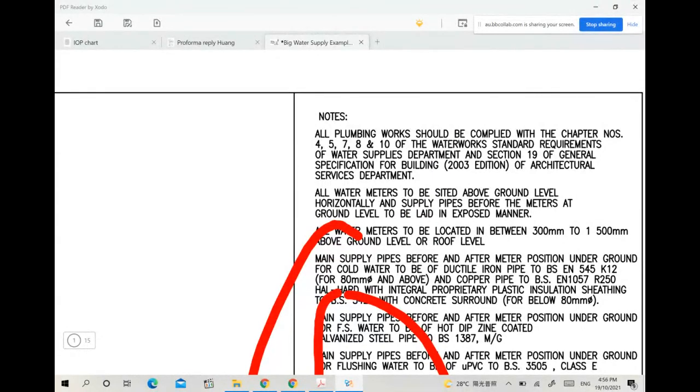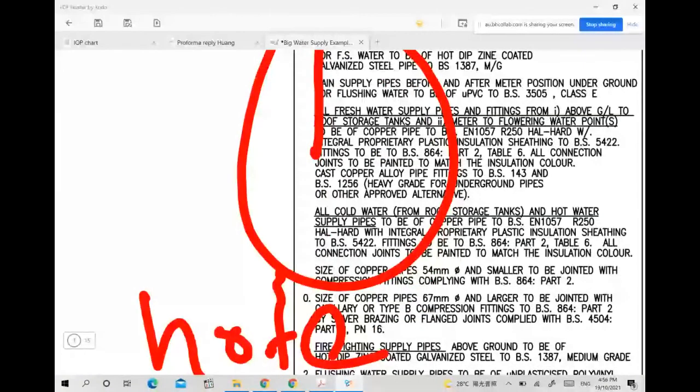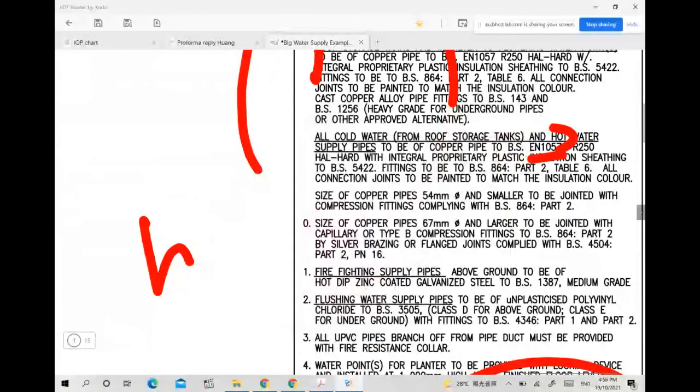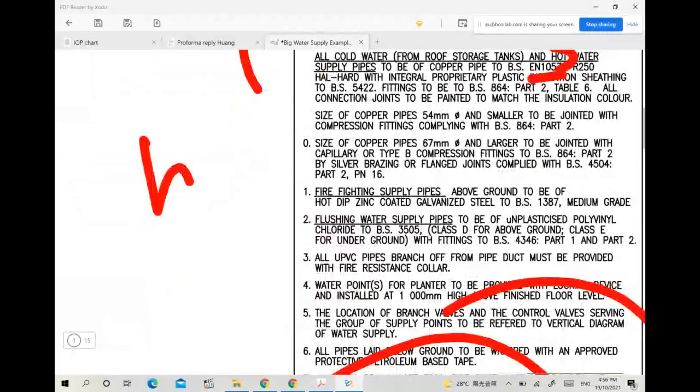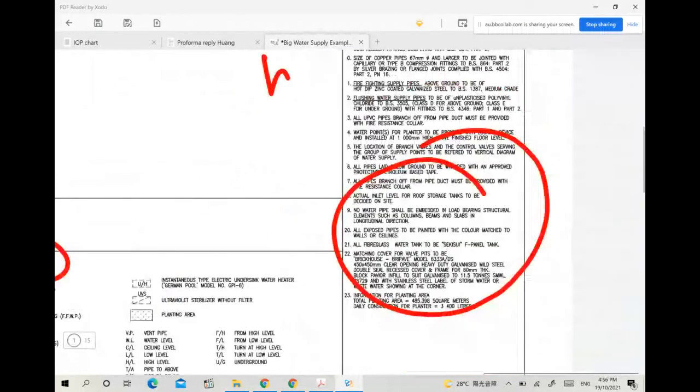That means sometimes, for piping without any notification of the pipe diameter, it must be 22 mm. Because for the last section of the pipe, you are not required to write down the dimension. So we may use this one. And all the pipes fulfill the British standard. So there may be a lot of information in here, okay? Understand? So this is about something you can't show in the drawing.